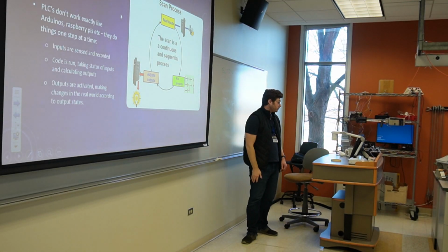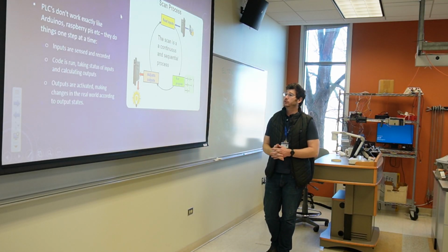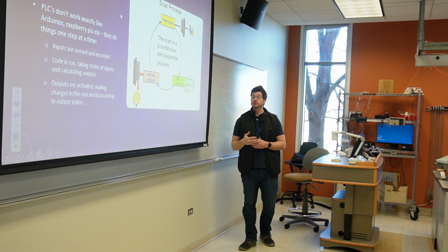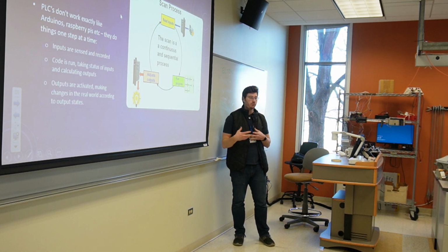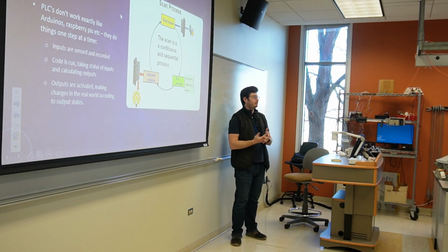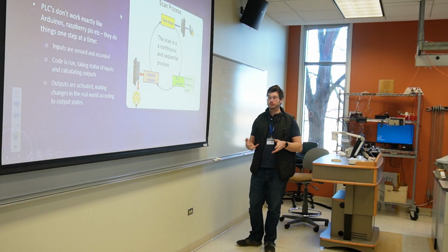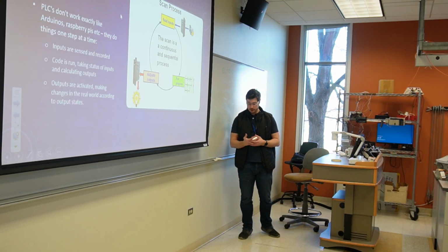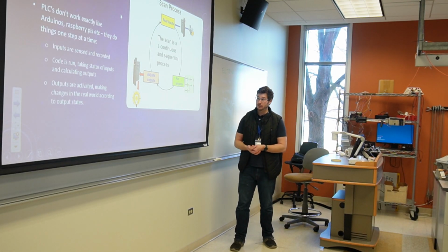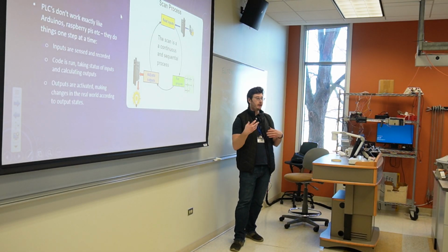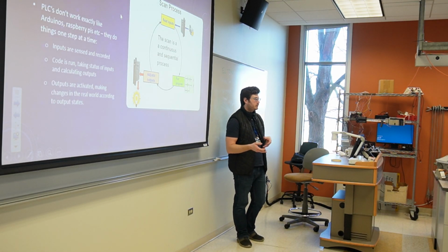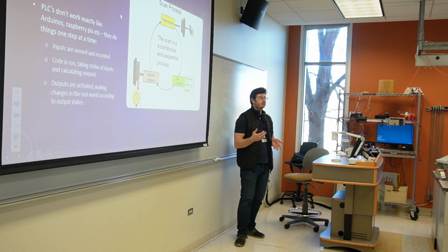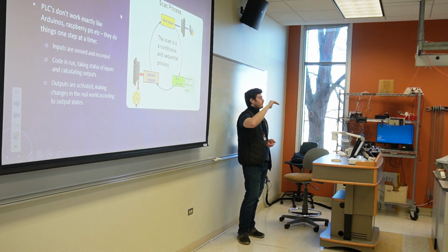All right. Okay, so one thing to get into, I've referred to this process before. It's that PLCs are designed to run their code differently. It's in a much more safe and reliable and understandable fashion than microcontrollers typically run. So your typical microcontroller, your small pocket calculator, your Arduinos, things with processors in them, have code that is created from a compiler. So we write down code in our IDEs, if else, do this thing and do that thing, run calculations. And we more or less assume that it'll run the first line, and it'll run the second line, and it'll run the third thing.